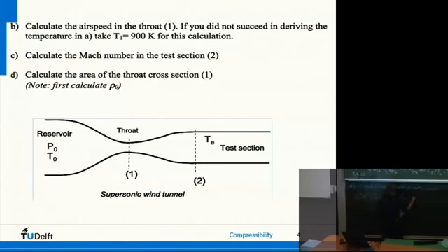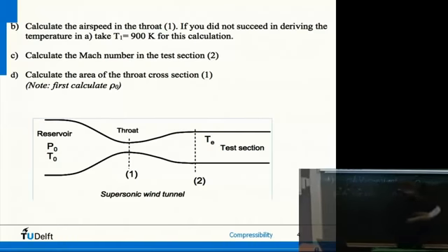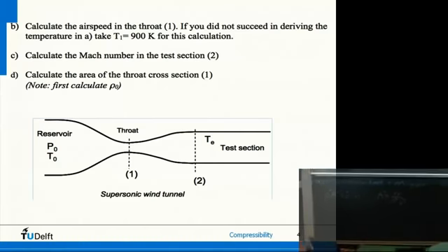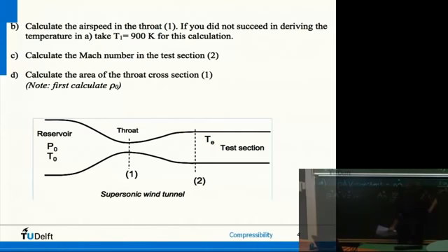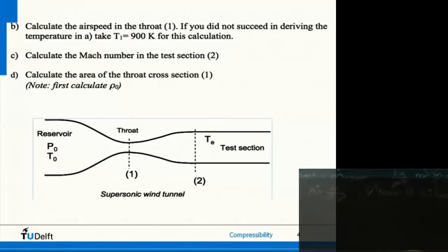It is then mass flow divided by density in the throat and speed in the throat. Do we have the density in the throat, and do we have the speed in the throat? Speed, yes, right? I think we computed it here. So that one we have from B. So V star from B, V star was 640 meters per second. So if there's any way to compute rho star, we're done.